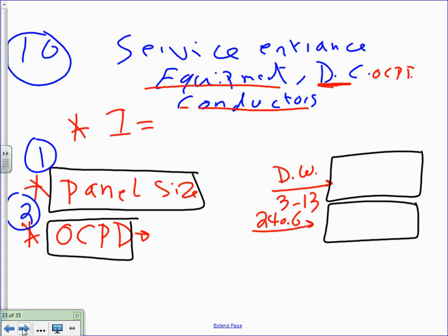All right, so 304. I need to take the 304, divide this, don't forget the K, by the voltage system, which is 240. Now, if the voltage system was 208, 3 phase, what do you do here? You divide by 208 times 1.73. It's the only difference at the end. But of course, we can't because the system is 240. What's the full load amp of this? 1,200. 66.7. 67. Let's do that. 67 amp.